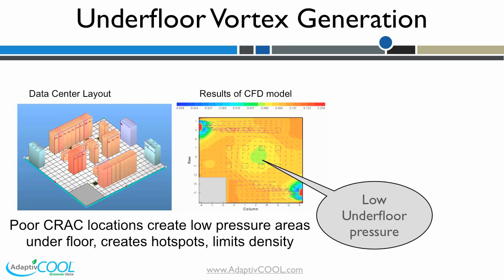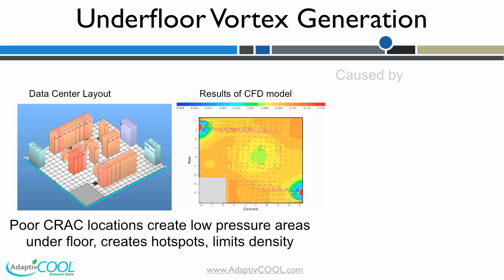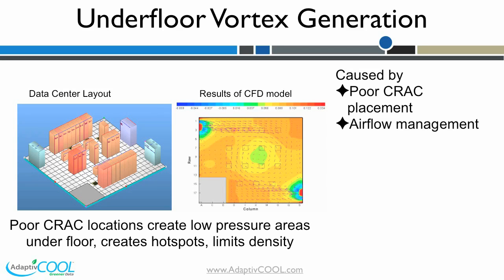The center of these vortices is at low pressure, so airflow from the tile is reduced or can even be flowing into the floor. It can be easily tested using the paper test mentioned before. To break up a vortex, underfloor airflow may have to be redirected using panels or diffusers. This can also be resolved using fan-assisted tiles like Hotspotter.